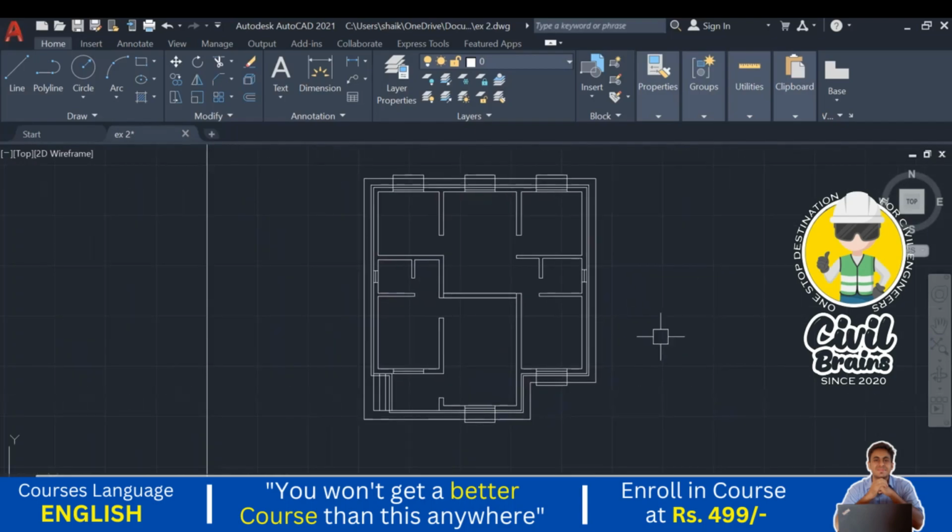Okay, and one more thing I just want to tell you. Whatever plan we are doing here, this plan is at sill level. So whatever things come above the sill level, what is sill level here? Sill level is the bottom level of the window. That is always called the sill level. So above the sill level, whatever things come, all those things we need to show in dotted lines.